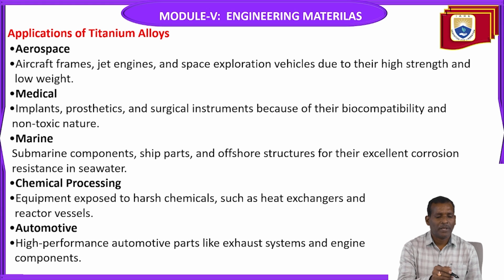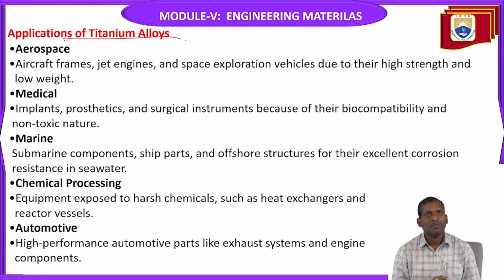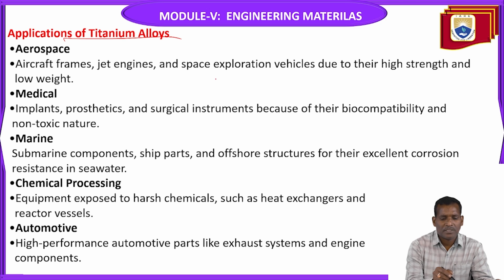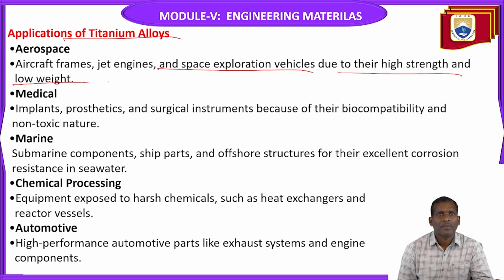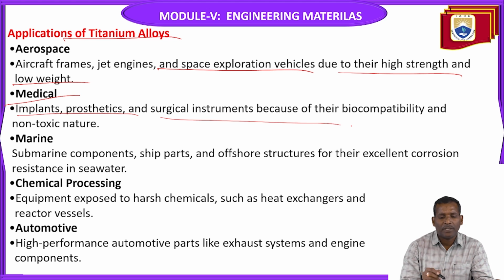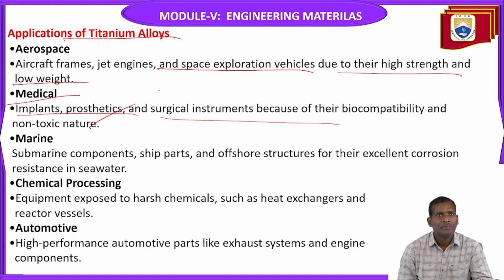What are the applications of titanium alloy? Aerospace applications, already we have discussed: aircraft frames, jet engines, and space exploration vehicles due to their high strength and low weight. Medical applications: implants, prosthetics, surgical instruments because of their biocompatibility and non-toxic nature.